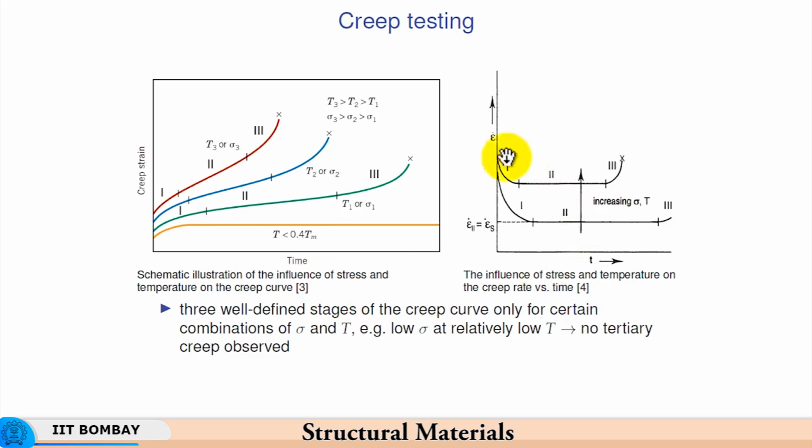So, this we have seen already, but then if you look at the strain rate versus temperature curve at different stress levels, at high stress levels, of course, the range at which the creep rate would remain constant is reduced significantly. As you see here, at lower stress, or at a higher temperature, the strain rate is maintained over a long period of time. So, a constant strain rate stays for longer duration, whereas if either stress or temperature is increased here, then you get a much smaller duration of constant strain rate regime, and the strain rate is also much greater than when the stress was less.